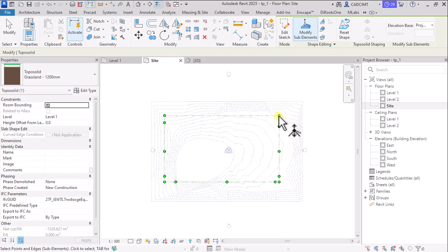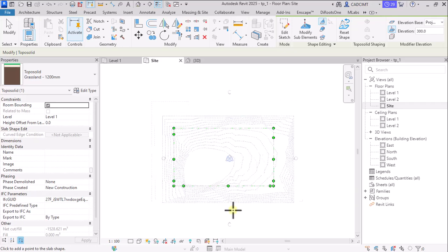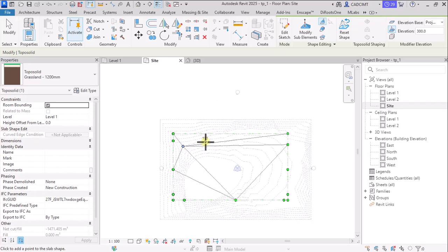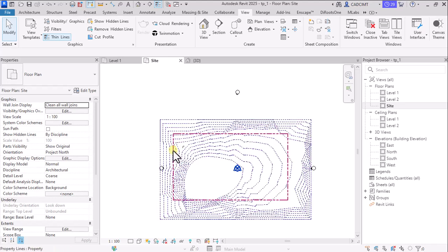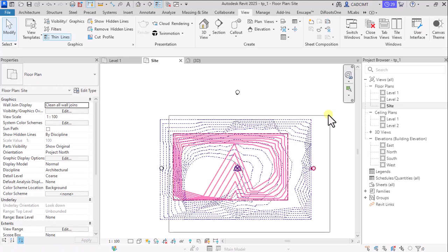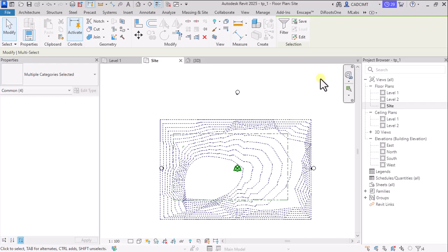So we have existing elevations here, and I wanted to have the existing elevation. So I go for add point here at 300. So I want to change it to 300. I want to make it flat here at 300. I want to remove the extra surfaces through cut and fill. And then you have this point over here, which is the newly created point.